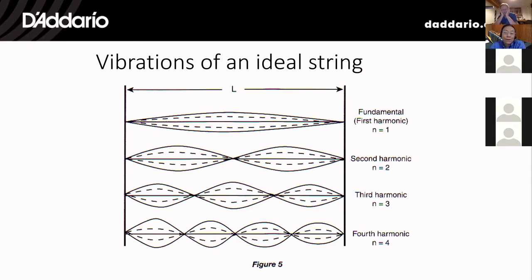All structures will vibrate at multiple and different frequencies, but typically those frequencies have no simple relationship to each other. One of the exceptions is an ideal string. In an ideal string, a distinct single tone is possible because the string vibrates harmonically. That is, all of its higher modes of vibration are exact integer multiples of its fundamental frequency. And when a string vibrates harmonically, the ear tends to identify the fundamental frequency of that string as the source of a single distinct pitch.